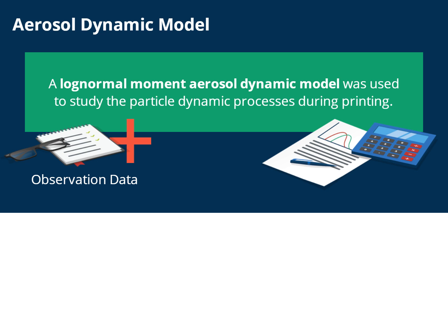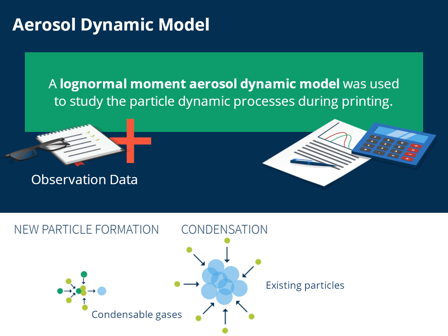Investigated processes included new particle formation, particle growth by condensation, and coagulation. These were included in the governing equations. The key parameters of particle distributions, including total concentration, mean size, and deviation, were calculated by solving governing equations using the method of moments.